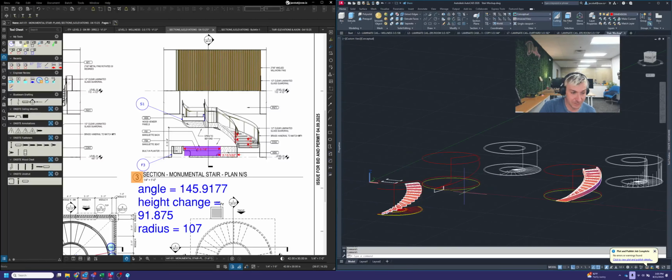You just got to know how to do the math. Got to know that everything needs to align. You need to be perpendicular to your helix when you sweep. Any sort of variation there, of course, is going to distort the profile, and you'll end up like Synergy, name drop. You can't do that. You need it to be perpendicular, and you also need it to be vertically up and down to that curve, because otherwise it will get distorted, and you don't want that. I promise you, Jake will come knocking at your door and be like, "Why did you do this?" So yeah, really important stuff.